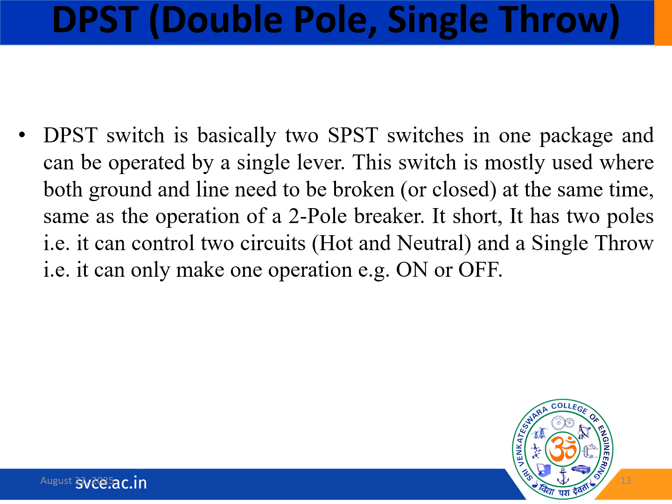So we have seen some instruction about this DPST. Commonly it is used where both line and ground must be interrupted for safety, or it can be used for compliance. It operates similarly to a two-pole circuit breaker, and it also provides reliable disconnection of both paths.